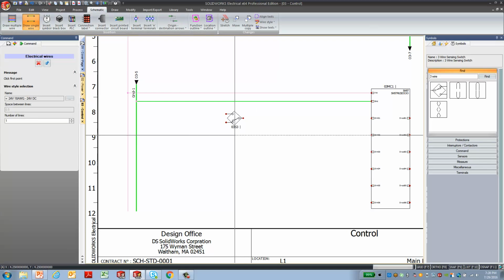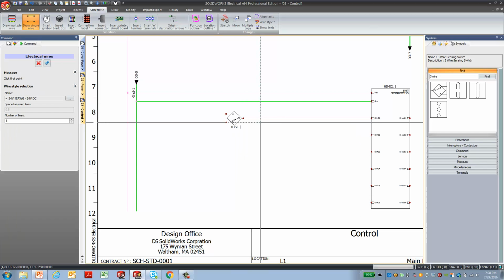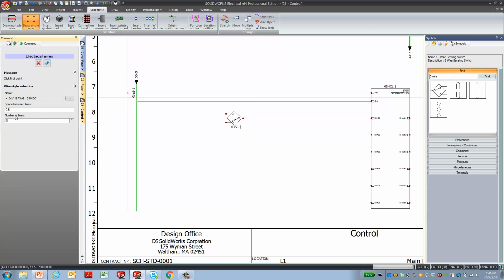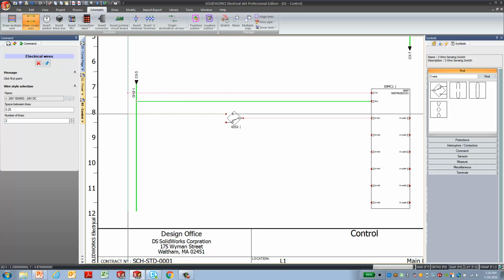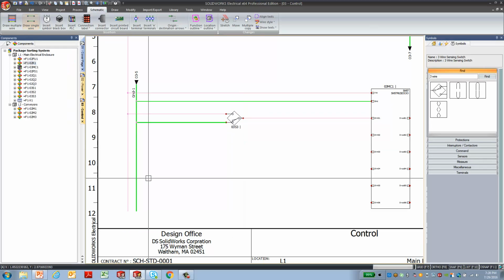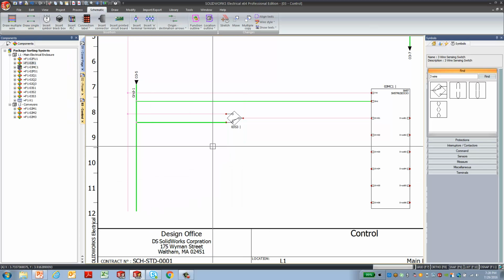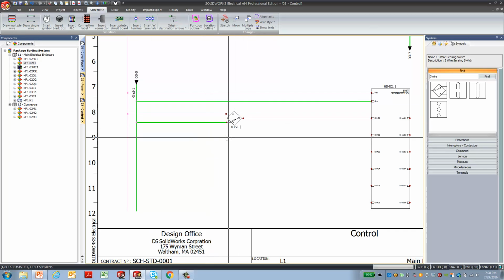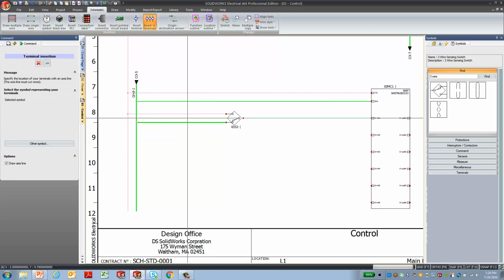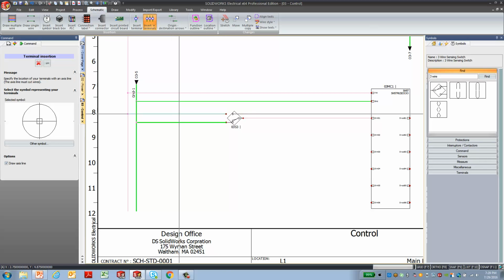And let's go back to our wire tool. I'm going to connect the output here to the input. And now let's add 2 wires spaced 1/4 inch apart. This allows me to create both the power and the ground wires at the same time. And since it's very unlikely I'll be running 3 separate wires out to this sensor, I'm going to use a terminal strip inside the cabinet that will allow me to attach a cable to go out to these sensors.